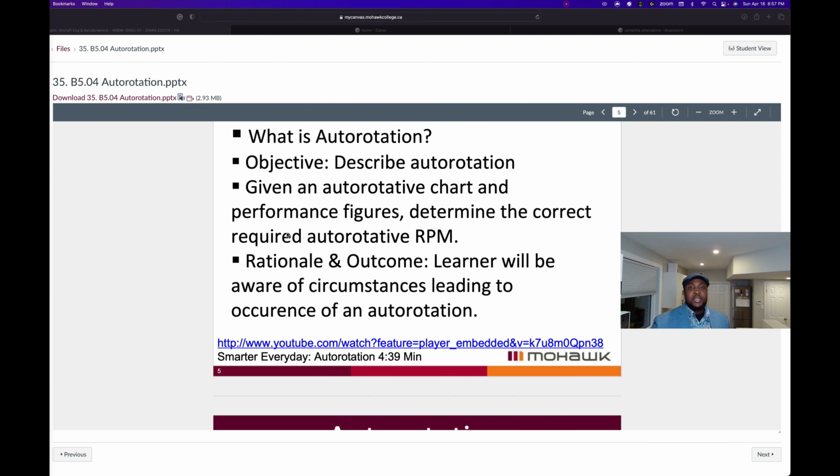As we discussed, during powered flight, the direction of airflow is down through, lift and drag are large, and the total aerodynamic force is well aft of the axis of rotation. So this is the location of lift and drag during powered flight. In the event of loss of power, the collective is immediately lowered.